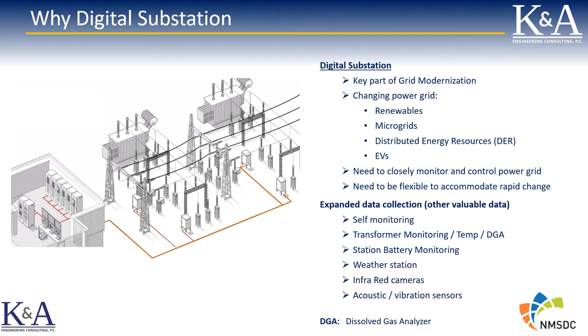It's completely self-monitoring. Just as an example, GOOSE messages are constantly being transmitted, even in quiescent states where the station is operating nominally and there are no fault events taking place. GOOSE messages are transmitted periodically, like once a second. So a device that's expecting to see a GOOSE message, if it doesn't receive it every second, will immediately set an alarm, which tells you there's a problem, which means you can go and fix it and have the circuit operational when you need it.